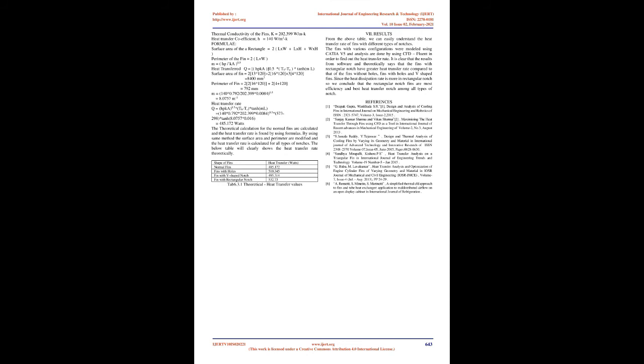Theoretical calculations. Let us consider a normal cross-section fin of length L, perimeter P, heat transfer rate Q, and thermal conductivity K. Gas temperature, Ta equals 298 K, 25 °C, ambient temperature; base temperature, Tb equals 573 K, 300 °C.